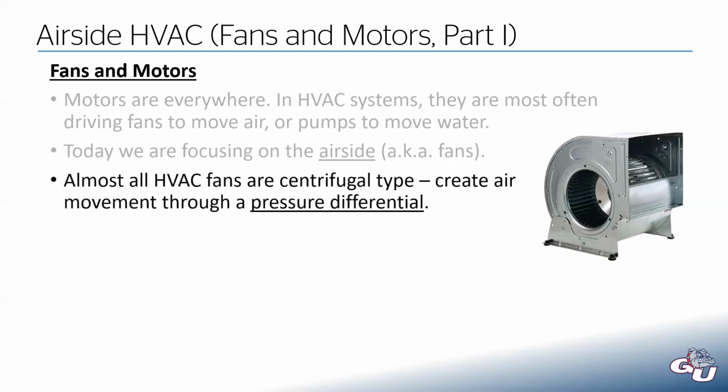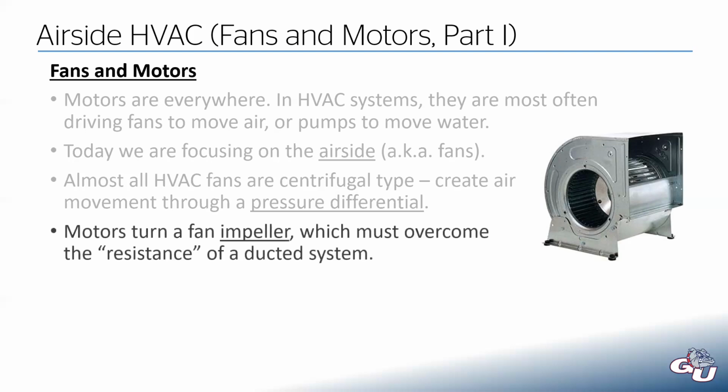Almost every HVAC fan we look at is what's called a centrifugal type fan. And all that really means is that they create air movement through creating a pressure differential. And I'll explain how that works here in a second. The idea is that within the fan is what's called an impeller, and that impeller is going to spin on a motor to make that air move, which I'll get into more depth here in a second.